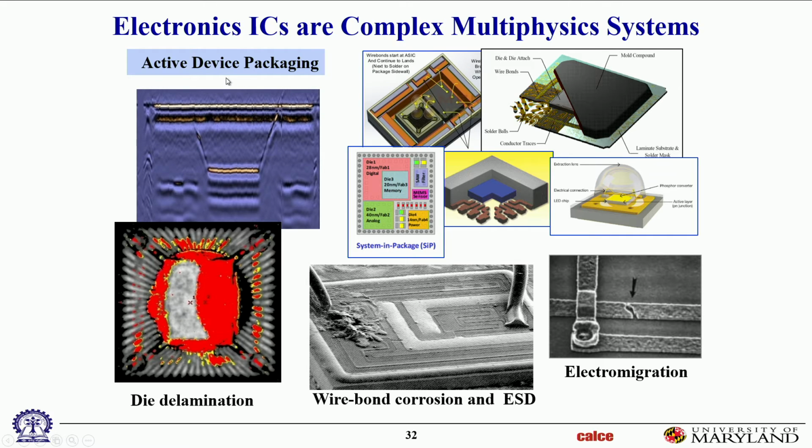So think about all active devices. And by active devices, I mean anything with a semiconductor chip in it. It could be a MEMS. So that, by the way, is a MEMS microphone. This is the MEMS sensor. This is the ASIC next to it. ASIC is application-specific IC. That's for the signal conditioning. So that's a MEMS microphone. That's probably in your cell phone. The microphone that picks up your sound looks pretty much like that.